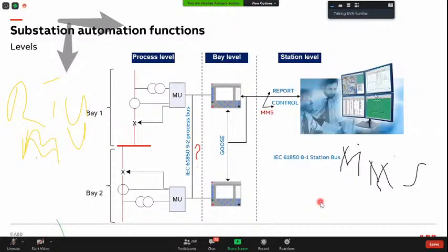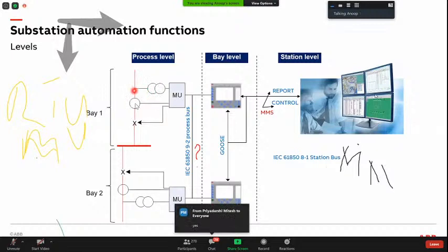There is a question like whether it's 4 to 20 milliamperes transmission or else, where in bay level? I think they didn't mention it anywhere. As I've explained, if 1000 amperes is flowing through this, the current transformer will have a 1000/1 or 1000/5 ratio. If 1000 is flowing, 1 ampere analog value is being sent here. It's a sine waveform, an analog sine waveform, not a DC one.